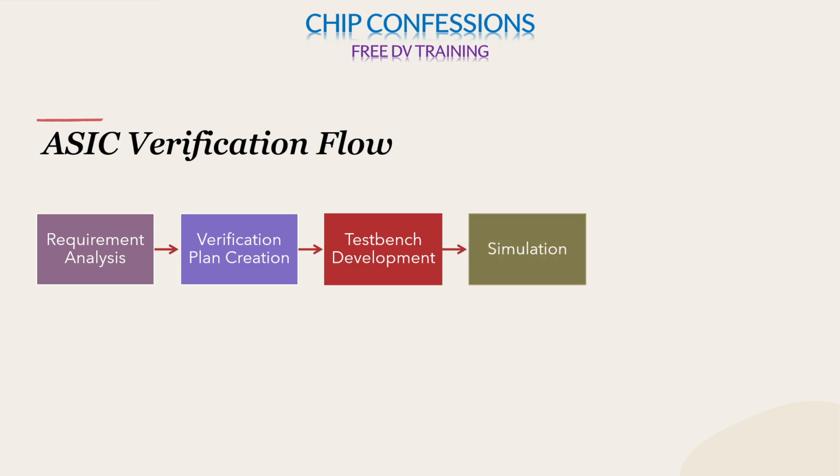Then we will have the simulation stage. Simulation is where you execute the test bench architecture you created. We will run this RTL design, meaning we will connect the RTL design with our test bench, and run that design code inside our test bench. We will check whether the output of the design matches the expected behavior. If there are any discrepancies, mismatches, issues or bugs, we will find them here, catch those bugs and try to fix them.